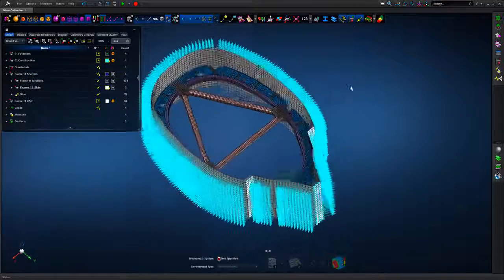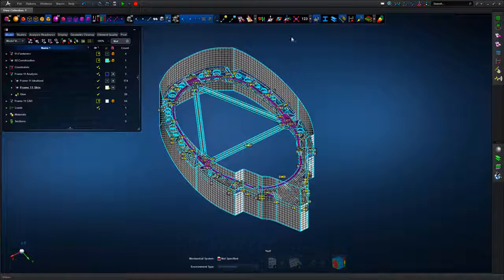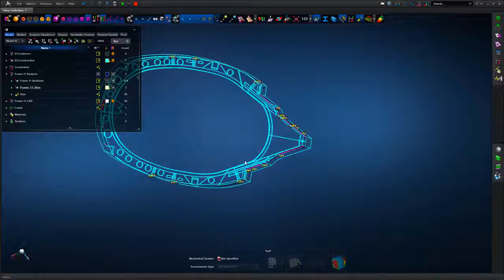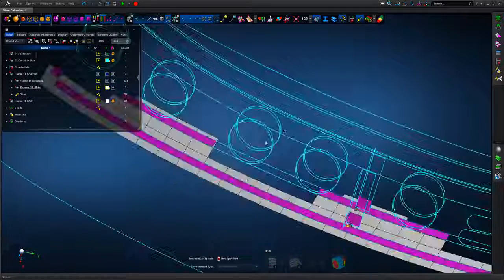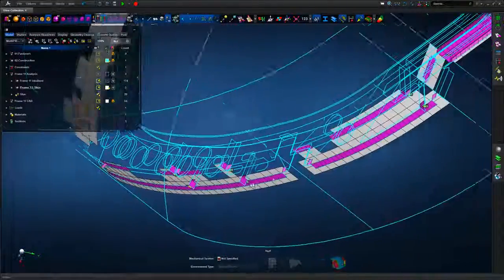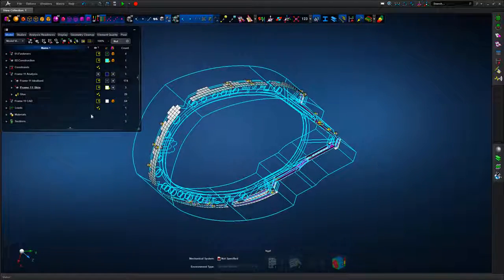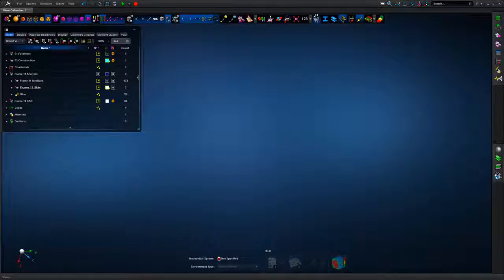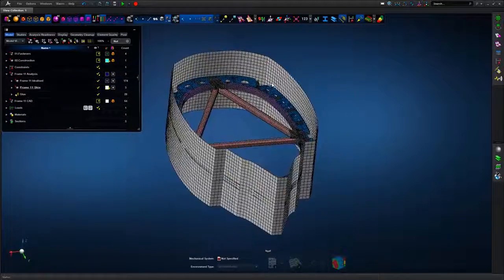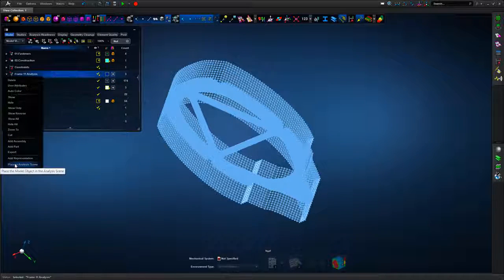So once we've verified and potentially exported the model, we can integrate the analysis assembly into a larger definition. So in this case, we've got a fuselage skin defined, and we glue the original assembly into the skin definition, and again, one of the previous webinars goes over the glue technology from a mechanics perspective in terms of load transfer, both for force and moment.